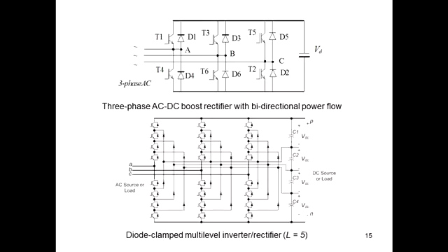And in contrast, this is a 5-level converter. This is again a circuit like this with bidirectional power flow, but each AC voltage waveform here, being produced from a DC supply, can have 5 levels, other than 2 levels. So it can produce more sinusoidal output. And there are control and voltage balancing issues and a few other issues which will be dealt with later towards the end of the course.